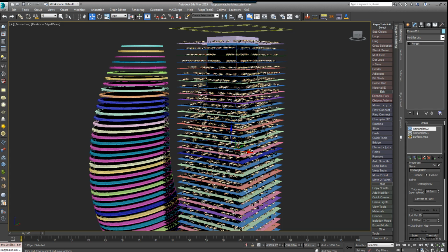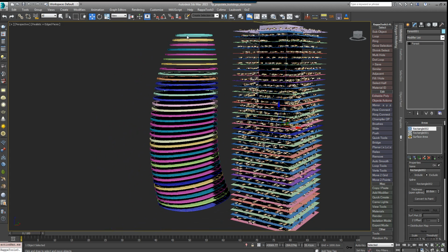But for buildings that have highly variable profiles, like this simplified example shown here, this would mean a lot of forest objects. So for these type of buildings, instead of using splines to exclude objects, we can restrict the scatter to particular material IDs. In this example, we'll offset the floor plate to create a perimeter ring of polygons and change the material ID. But before we do that, let's apply our existing forest pack object to this new set